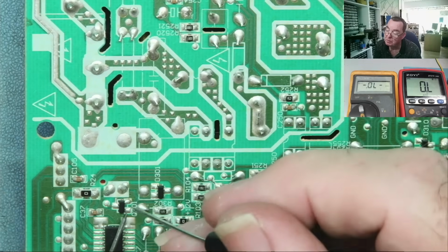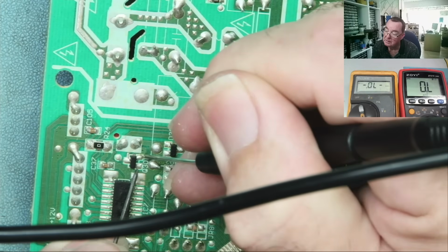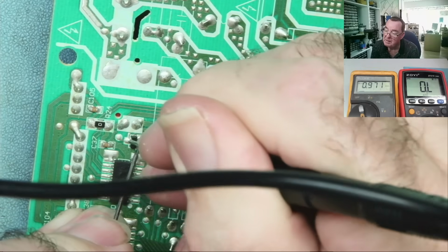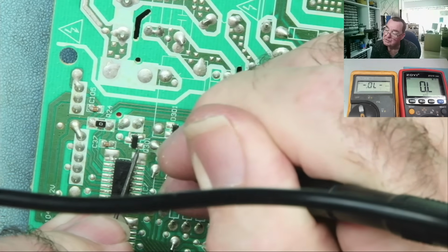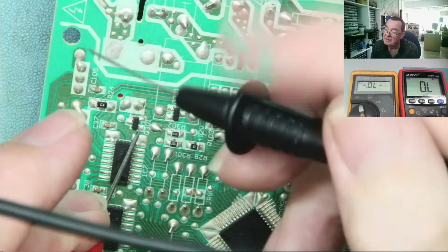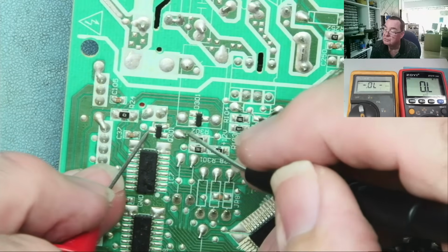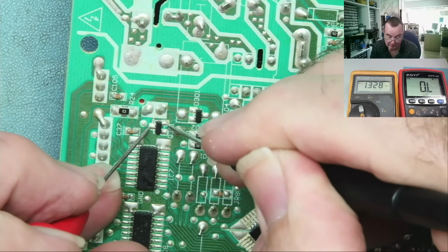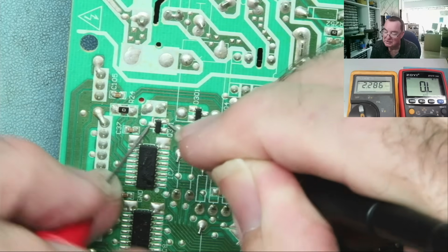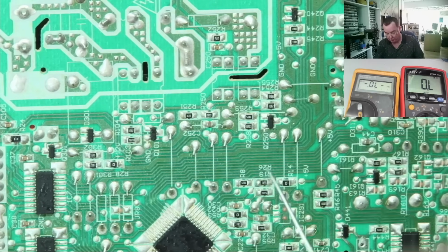This one, Q301. So this will be the base or gate. We go from here to here. We see a diode junction. Is the same here? Yeah, diode junction to there and there. So this looks like this is the red lead. So black for negative, red for positive, NPN. Yeah, NPN. It looks good, and we can just go between the collector and the emitter with a positive on the collector, which is a normal polarity for an NPN transistor, and the voltage is going up. So that's fine. That's those two. Let's go for another one, see what we have.